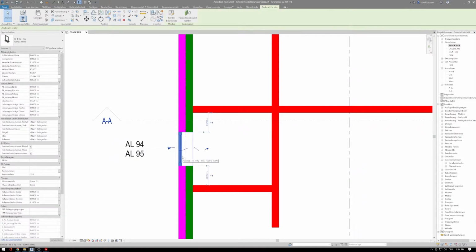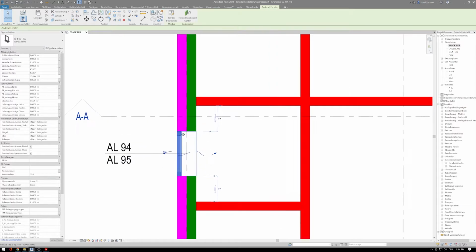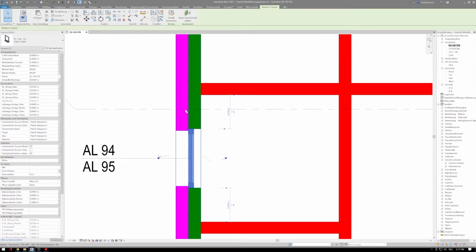First things first, what I want to do is arrange my construction parts, which are my Einbautiefe, my Abzug links, rechts, oben and unten. And then I want to change my width and height parameters. First I go to Einbautiefe and it has to be 0.2 meters. It makes it align to the edge of the core.